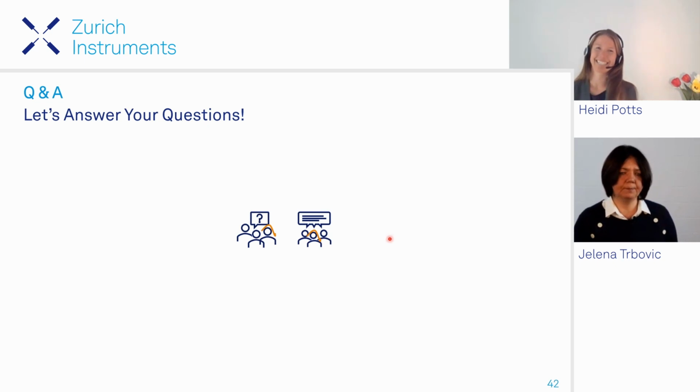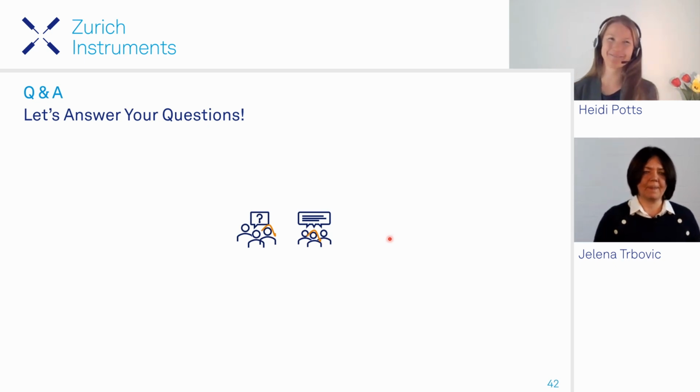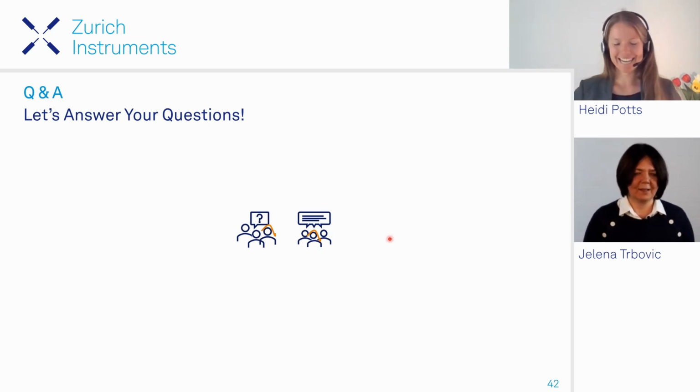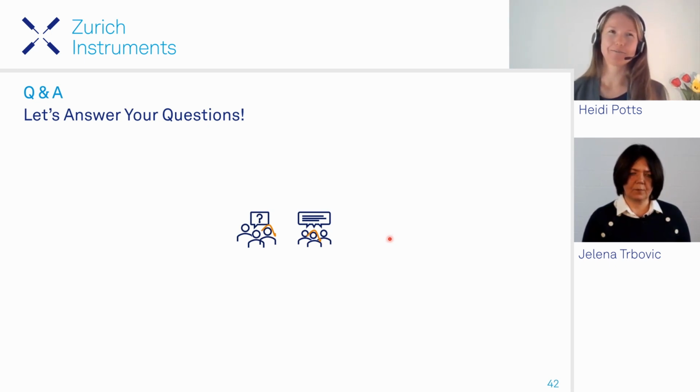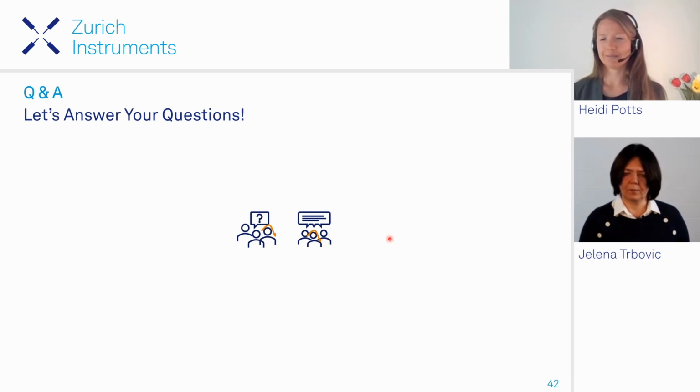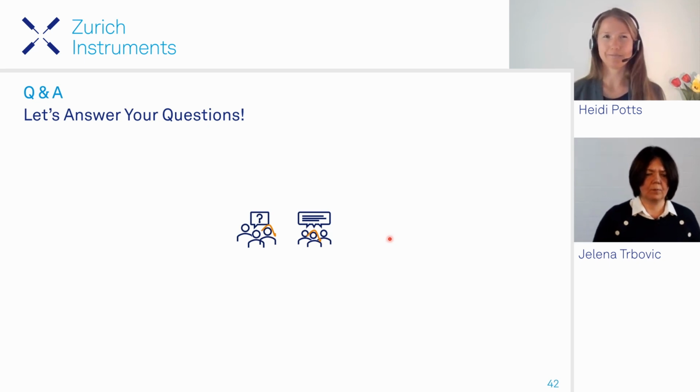Yeah, sorry, I cut this short at the end of my presentation. Thanks for asking. The cool trick there is that with the UHFLI, you can do frequency multiplexing. You can have one signal generated that consists of several frequencies, and you can demodulate at these different frequencies at the same time, at up to 8 frequencies.